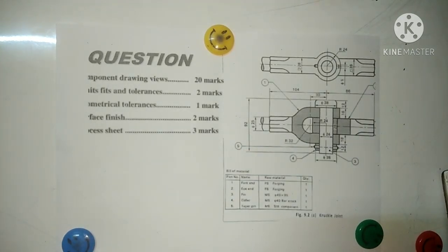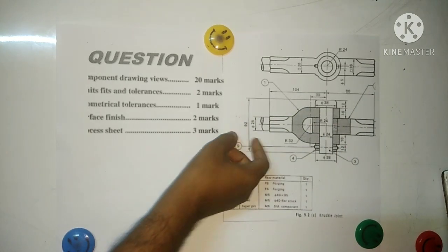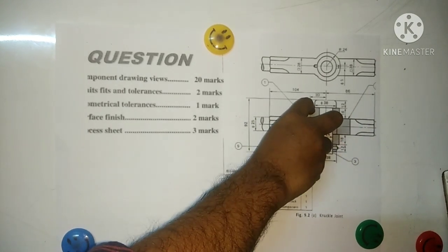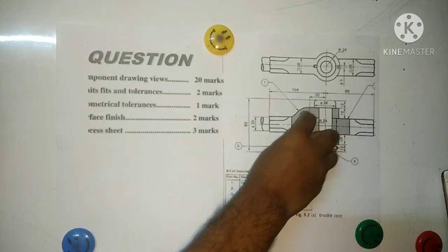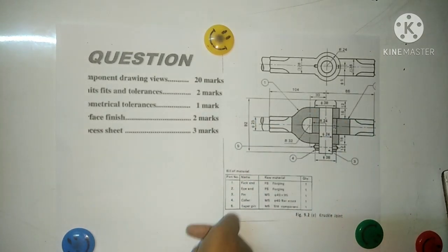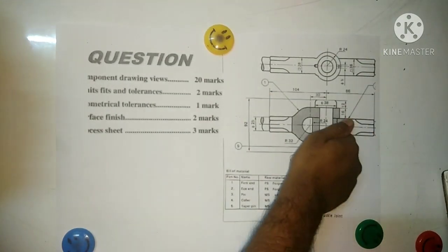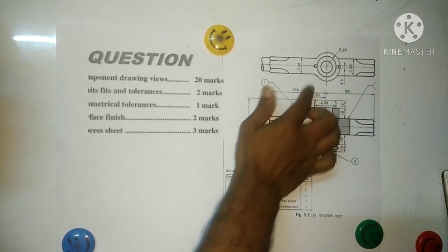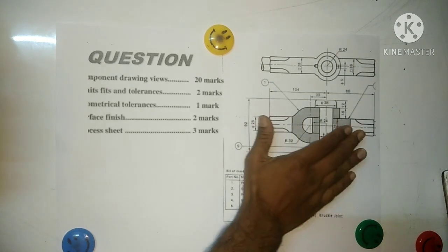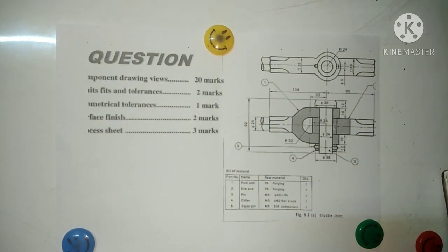So where can you find this? These are widely used in a tractor trailer. The tractor has to carry one trailer. You can see one fork end will be there, one eye end will be there. The eye end is connected to the trailer, the fork end is connected to the tractor, and the pin will be joined here. Then this coupling lets the tractor pull the trailer, so this becomes a single unit.